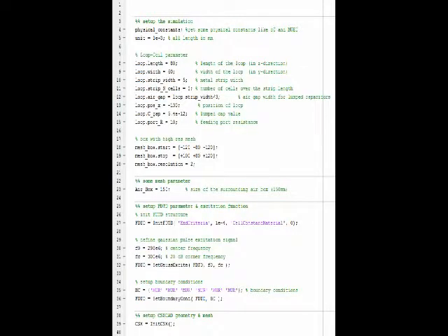Then we set up the FDTD parameter structures and the excitation functions. For the initializing, we have the init FDTD function taking the parameters and saving them into the FDTD variable. To define the Gaussian pulse excitation signal, we have the center frequency and the 20 dB corner frequency. This will go into the set Gauss excitation function, taking FDTD, F0, and FC as input, and then overwrite the FDTD variable again.